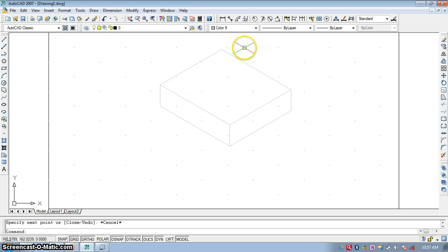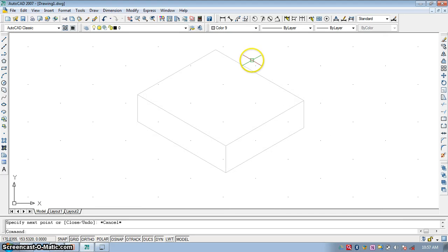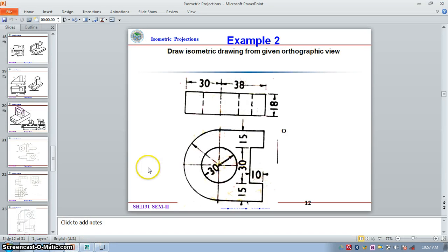So this is the box for isometric drawing. And then just observe the question. If you observe here, the top view is more clear than the front view, so you have to draw the top view first in a top plane. While drawing you have to observe both the views. If you observe, this circle is visible here. So having an 18 mm plate, that is drilled at the center here, and also a pocket is prepared here, and this one is a half circle.